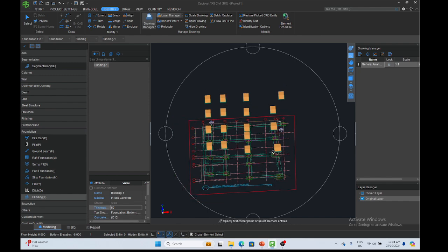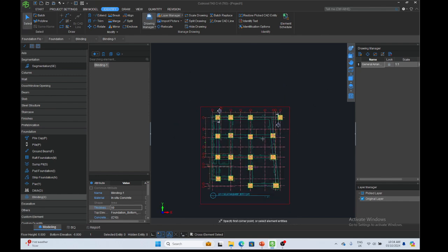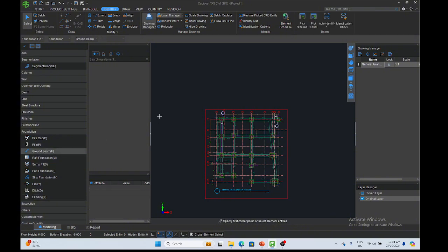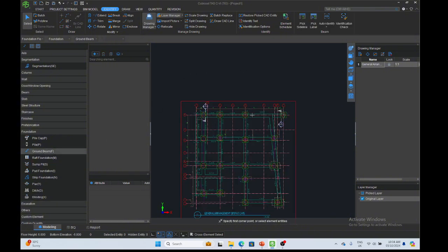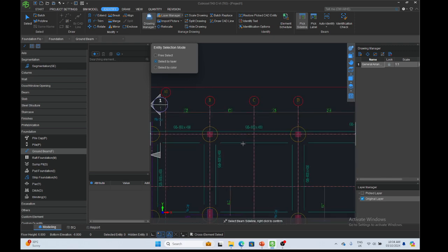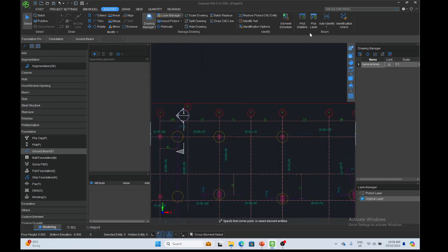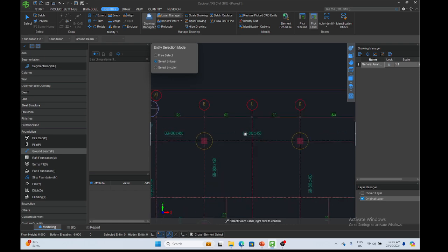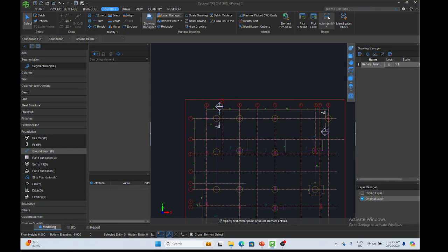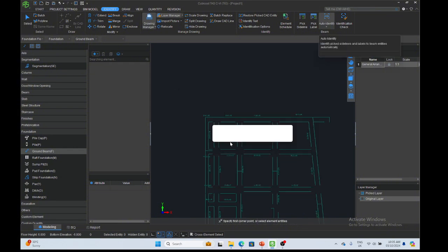After getting the blindings, our next target is to measure the ground beams. First we have to click on ground beam from our element list. Then we have to go to the Identify tab. There, we click on pick label, select the layer, right click to confirm, then pick label, select the label, right click to confirm. Then after that we have to change the elevation.